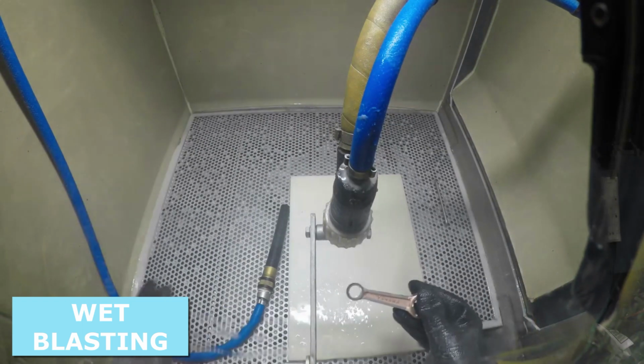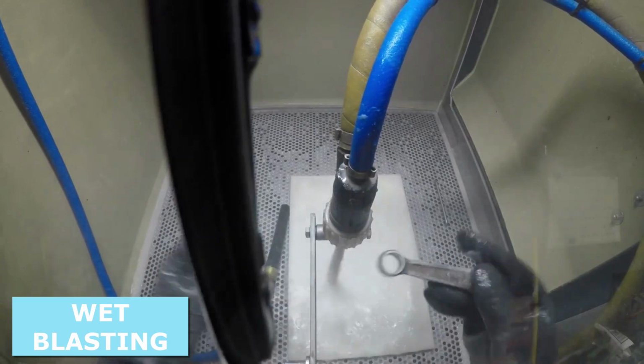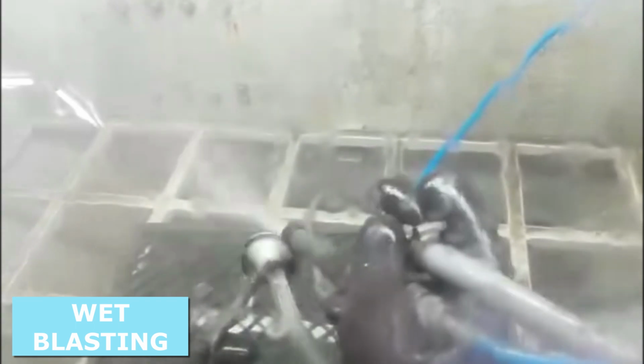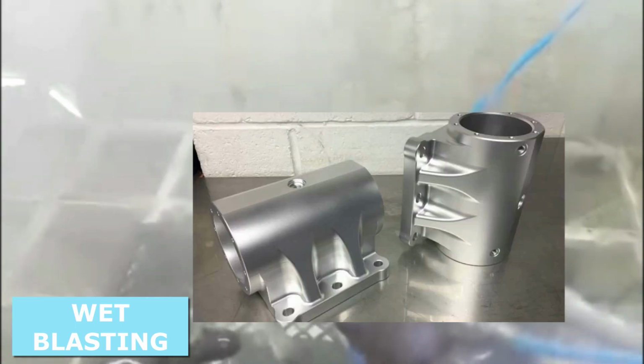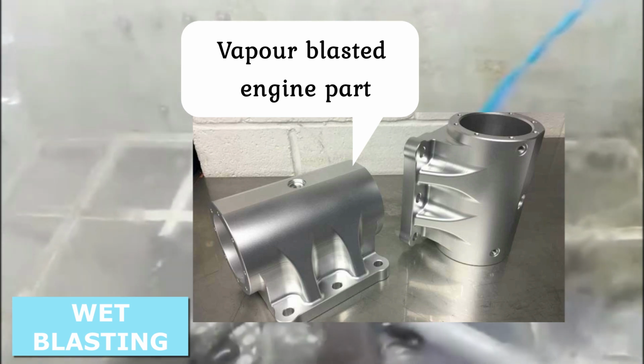Vapor blasting uses water and mildly abrasive media to clean metal surfaces without actually wearing away any of the metal, unlike sandblasting, which is a far more destructive process. Water buffers and lubricates the particles on impact, allowing very fine finishes to be produced without damage to the component. The end result is a fine finish, and no abrasive media is left behind because it is all washed away with the water, restoring components to a like new condition and producing a smooth satin finish.